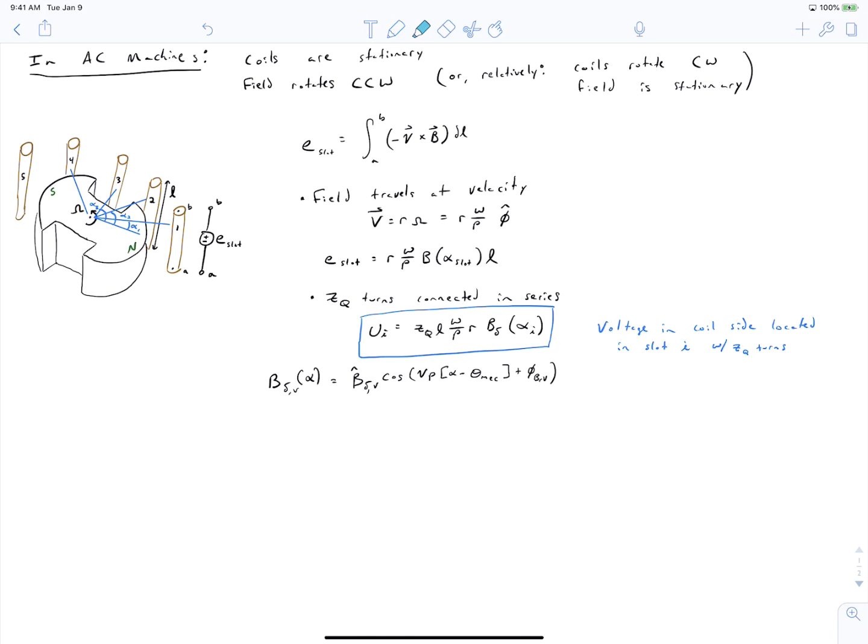So I'm specifically zooming in on one harmonic component of this. Our no-load magnetic field, our magnetic loading at harmonic V. Remember, harmonic V means it's an integer multiple of the number of poles of the machine. That's different from the harmonics N. So at harmonic V, not the velocity, but harmonic V, we've got a magnitude, and then we've got the cosine of V, that's our harmonic index again, times our number of pole pairs, and then times alpha minus the angle of our rotor, theta mechanical.